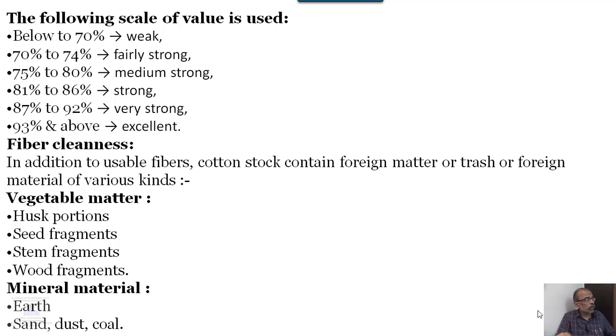Now whatever nominal strengths are there, when the observed value is 70% of that, this is to be taken in that sense. For a given cotton fiber, if a 25 g/tex value is there, and our fiber's value is 70% of this, then it is considered a weak fiber.